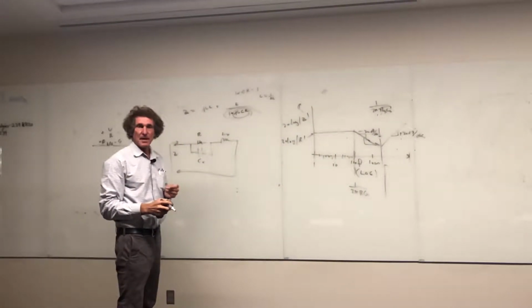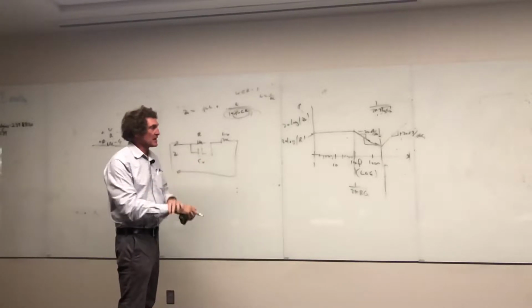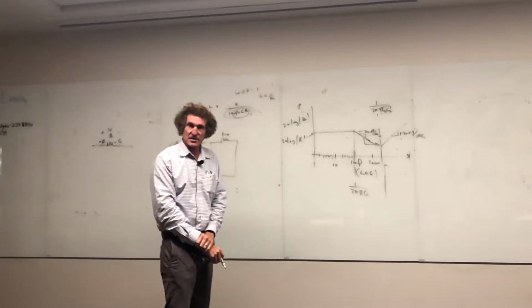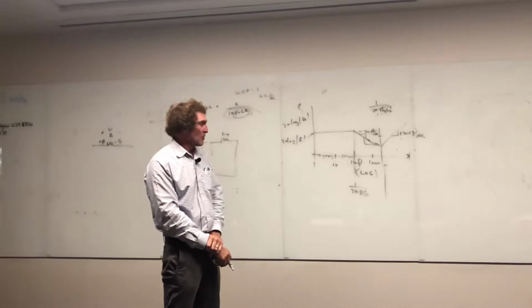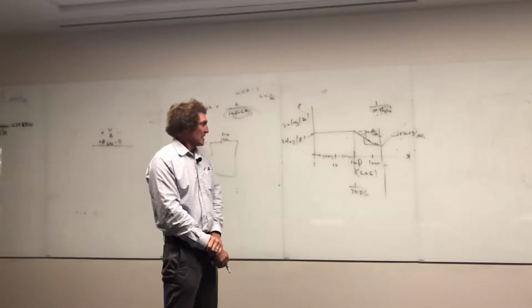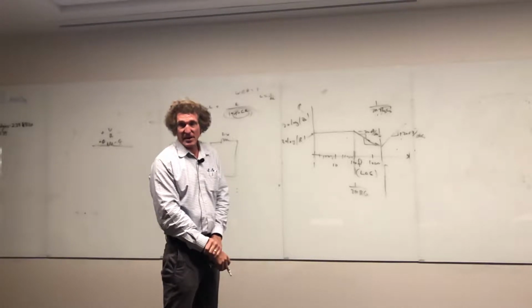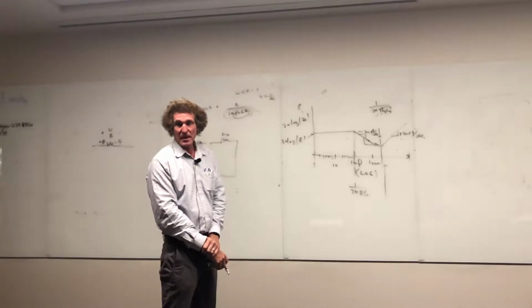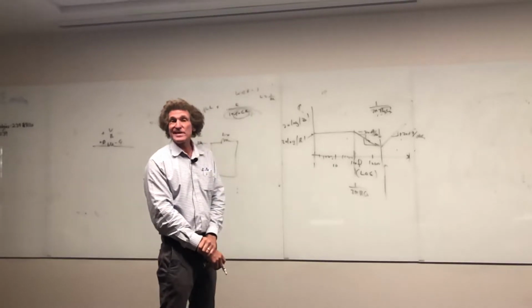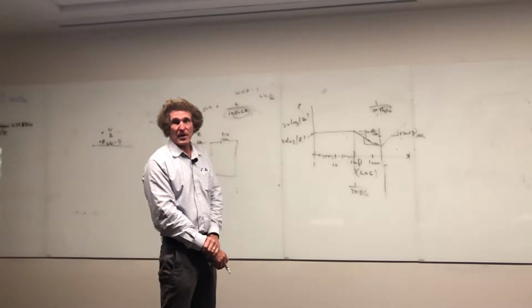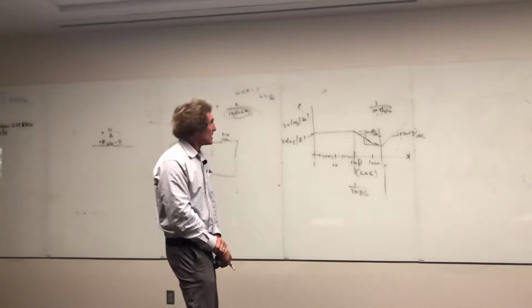Following on this? Now, what could I ask about this? If I said the resonant frequency was such and such, and the low frequency break was such and such, and R was such and such, you should be able to tell me what C and L are. Do you follow me, class? And it will always follow this shape. I'm going to give you problems like this tonight once I go through these. Everybody got that? So that's the shape of what a resistor's profile would look like versus frequency.